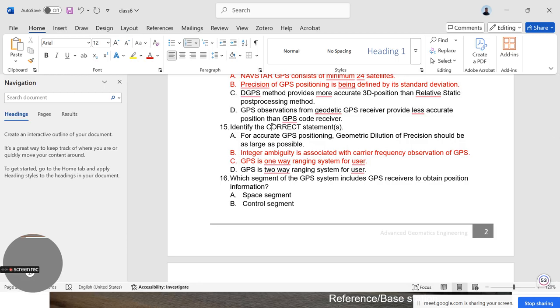Why is there a need to give data from the control station to the satellite? Because let's say the orientation of the satellite moved a little bit, so to correct it, or if it is not healthy, then what to do. Those corrections go into our ephemeris and almanac data, and using that we also make calibrations and validations in the satellite from control stations. So for control stations, it is a two-way ranging system, but for users, it is a one-way ranging system only.